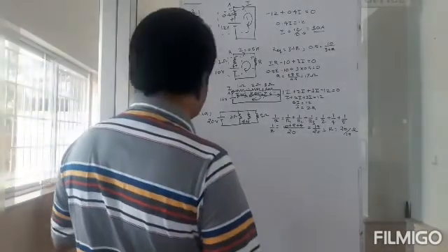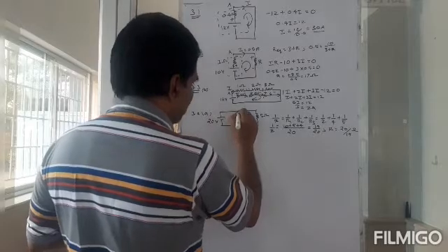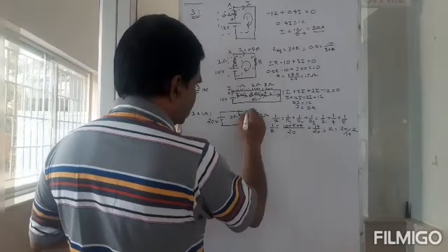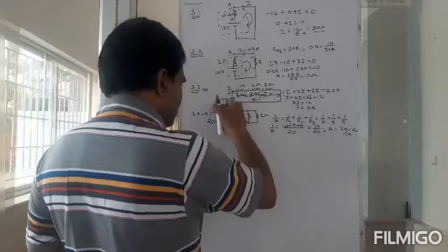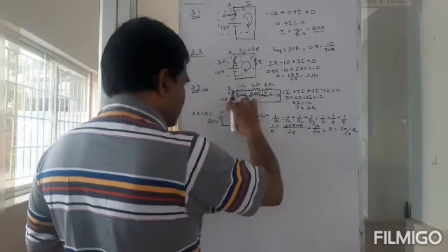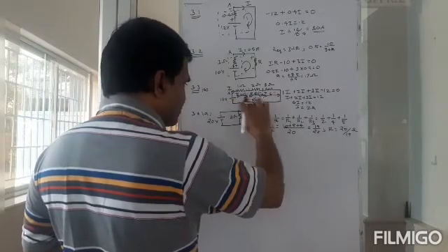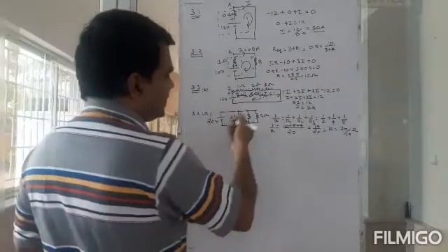Okay, and that battery is EMF of 20 volts and negligible internal resistance, so I don't have to worry about the r, that small r part. I can completely ignore that. And this is what I've got. Okay, now this voltage will be applicable across all the 3 resistors. The voltage across 2 ohms is going to be 20, then 4 ohms is also equal to 20, and 5 ohms is also equal to 20. So then what would be the current here?